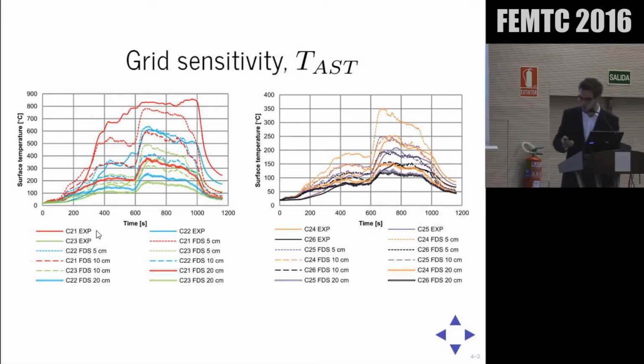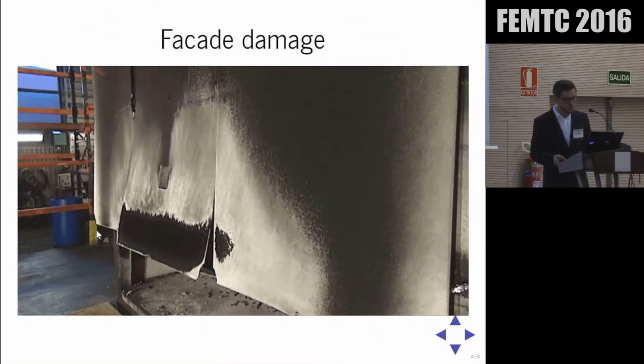But at the position closest to the fire here, you see that the FDS adiabatic surface temperatures are lower than the modeled plate thermometers. And that's a contradiction to what I just said. I don't know if you have noticed, but the shape of this first measurement line here is different compared to the other ones. The reason for the strange shape of the first measurement position could be due to the facade cladding, which may also explain the lower temperatures.